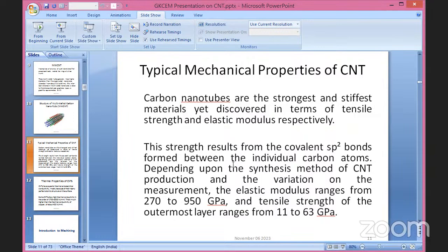But mind that CNT alone may not be used in many cases, but you can put CNT into some other substrate material and improve the overall property of these mechanical structures or some other kind of structures. And this CNT can be used to make alumina somewhat toughened, and then you can use it as cutting tool material. That we have actually tried.